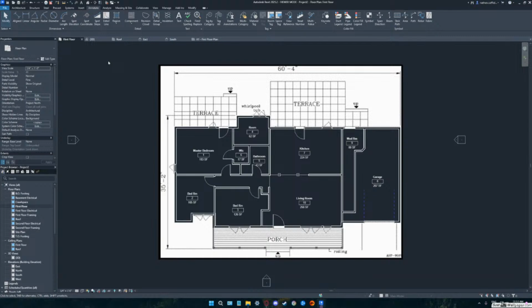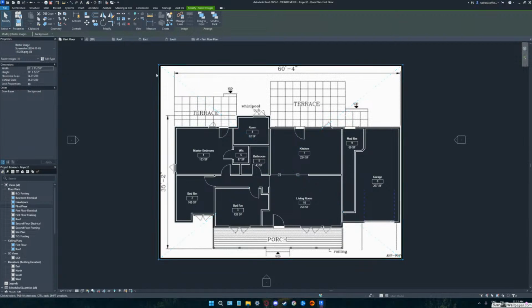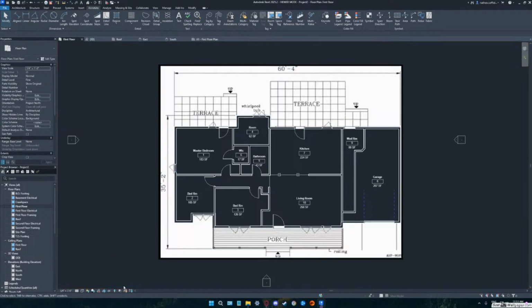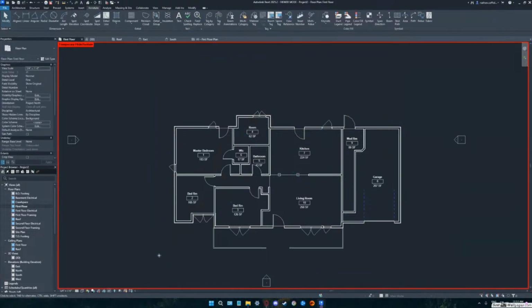Okay. So if you would do me a favor and pick the image that's in your screen and do an HH, and that's temporary hide. That's down where those sunglasses are, and hide object is what that just did. And you would hit those eyeglasses and hit reset if you want your image back on. Well, you can turn it on and turn it off. That'd be fine.